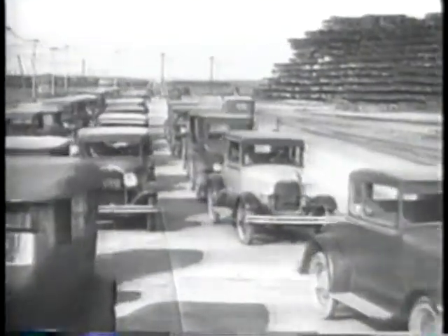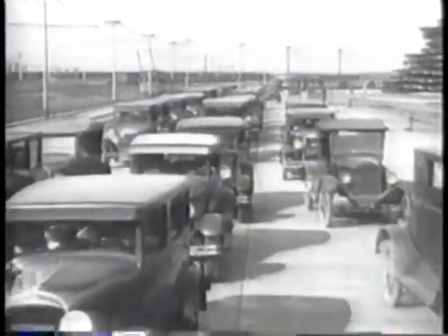If the front structure is too stiff, it stops the passenger compartment faster in a frontal collision, putting greater deceleration forces on the passengers. Older vehicles that were not designed to crush the way today's vehicles are very often appeared undamaged in an accident, but their occupants were often severely injured within the unyielding structure. If the structure is too soft, it will not absorb all the crash energy as it crushes. At the end of its crush, the passenger compartment and passengers will be forced to absorb the remaining energy.